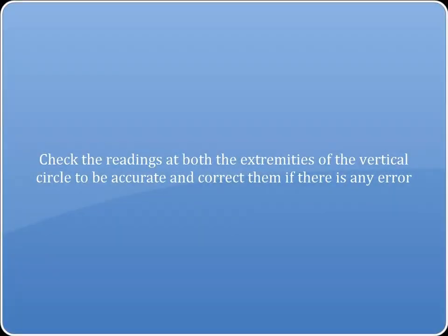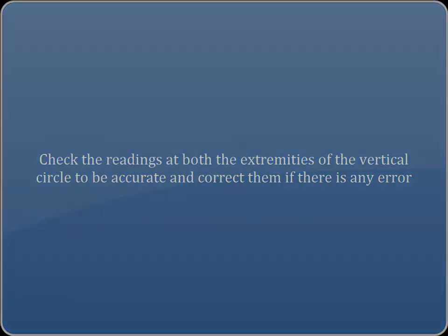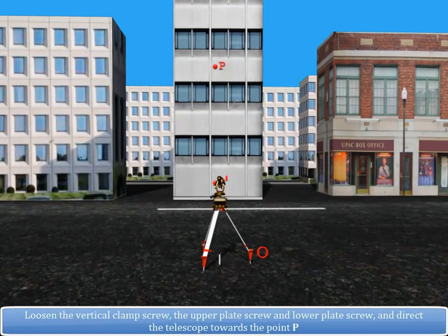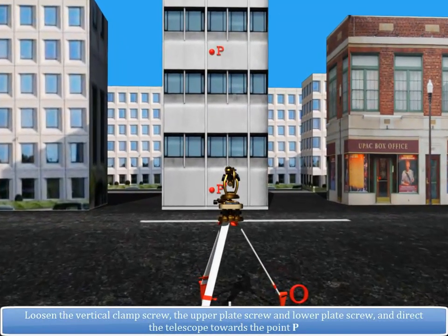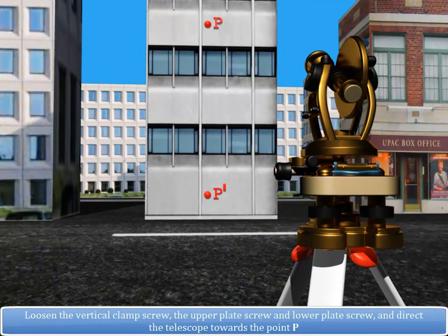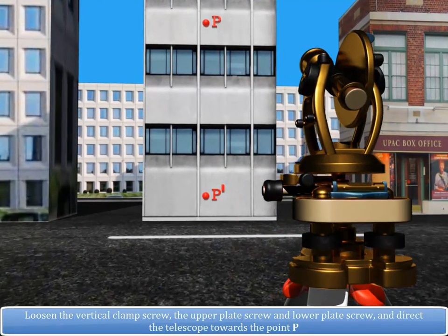Check that the readings at both extremities of the vertical circle are accurate, and correct them if there is any error. The temporary adjustments of the theodolite are to be done at station O. Loosen the vertical clamp screw, the upper plate screw and the lower plate screw, and direct the telescope towards the point P.